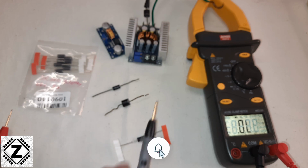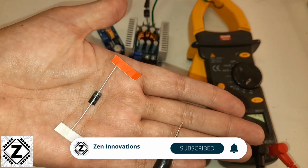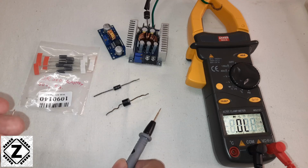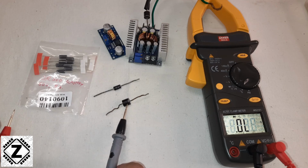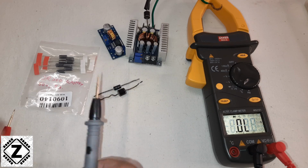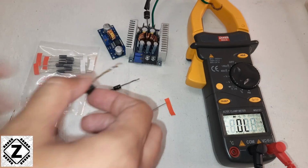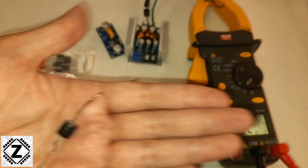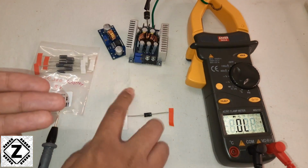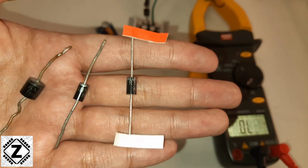Now at this point you might be thinking that, well, if Schottky diodes have so many advantages, why not just use them everywhere? Why even do these things exist? These things should not exist, right? No, you're wrong. These general purpose silicon rectifier diodes also have some advantages. For example, one thing being cost. These things are much cheaper. You will get them for around say 5 rupees or 10 rupees per piece. On the other hand, a Schottky diode will cost 45, 50, 60 rupees per piece.